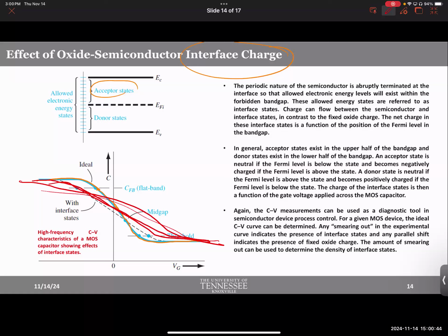After you make them, I already told you in the very first lecture, MOSFETs are smaller than virus and bacteria. You cannot practically go and see them, and you make billions of them. After you make them, how can you go down and see the interface? You'll be surprised to know the interface is only a few atoms thick, 5-10 atoms. You cannot simply go and see, oh, we have a bad interface. No, it's impossible. You have to use this type of macroscopic properties to back calculate and understand what's going on.